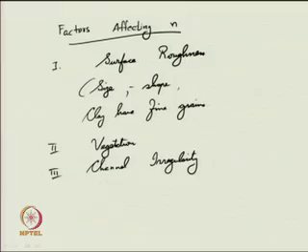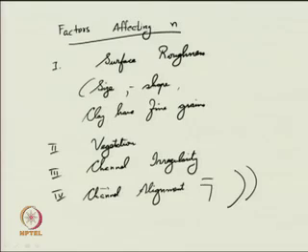way. For example, if there are sandbars coming into the picture or sand waves that may obstruct your channel flow, your roughness coefficient is going to increase. So, that you need to take into account. The next factor which can affect your roughness coefficient is channel alignment.